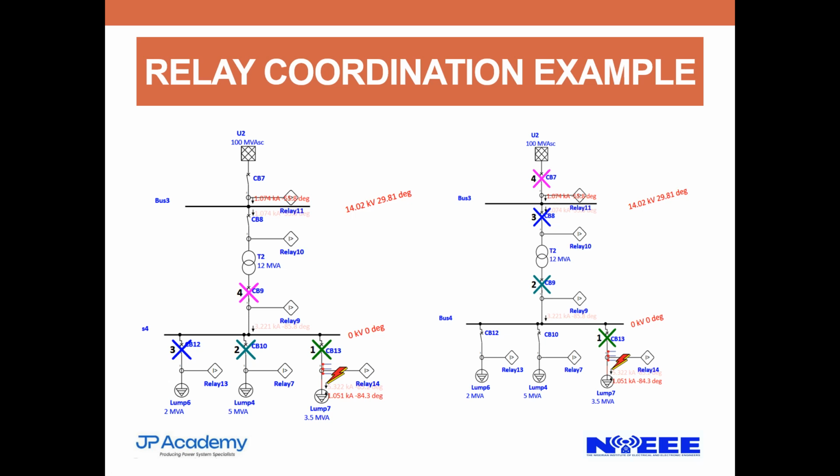So we are using that effect as an actuating parameter for our relays. A transient change in the magnitude of current is what we are using as overcurrent protection. We can also have overvoltage protection. We can have frequency protection. I don't know if that's clear.